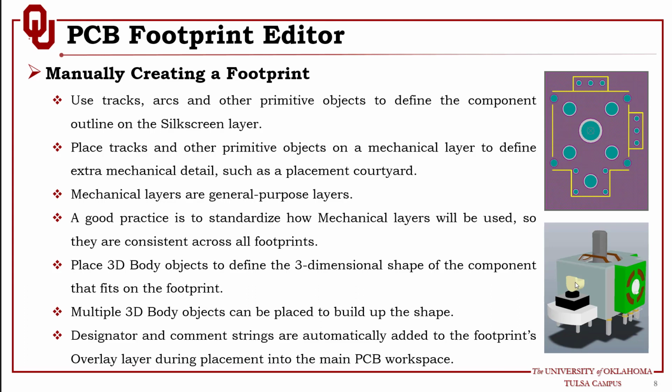You basically connect the outputs of these two potentiometers to analog-to-digital converter pins, and you read the output, one for the X axis and one for the Y axis. Usually these are 10 kilo ohm variable resistors. So if you have a 3.3 volt supply on the first side and ground on the other side, you can measure the voltage. Your voltage will vary between 0 and 3.3 volts based on the position of the knob. It's very simple and very easy to use as well.